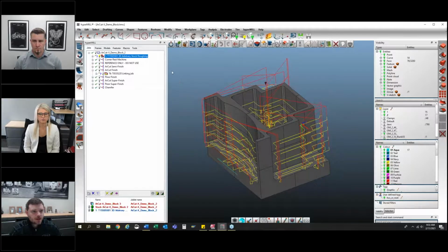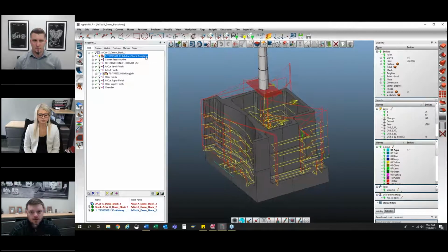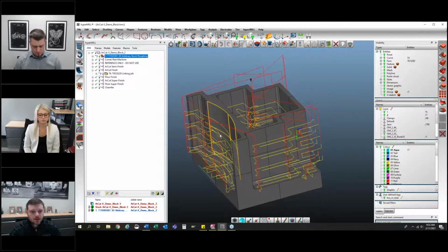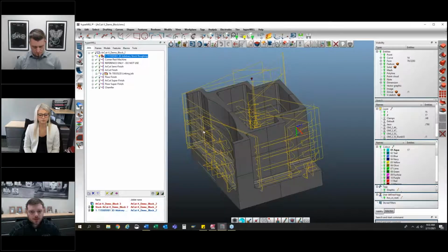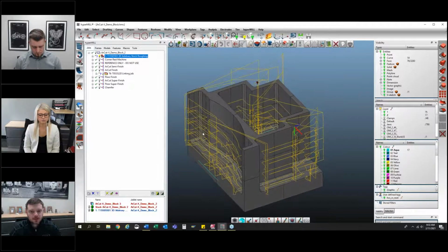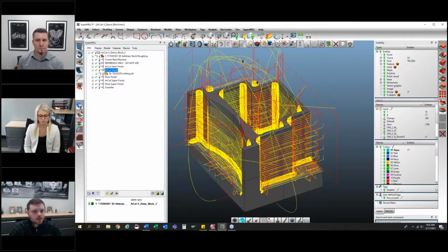But the first operation is with a 12 millimeter AX FPS aluminum rougher. You'll see that it can helical bore in very heavy into the material, and then it takes a full 80% step over to rough through that material, and it doesn't need a dynamic cut at that point. And then the next tool is just switching straight over into the R-Cut tool. Turn that on.